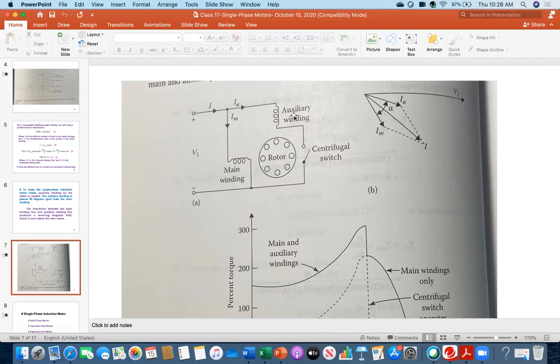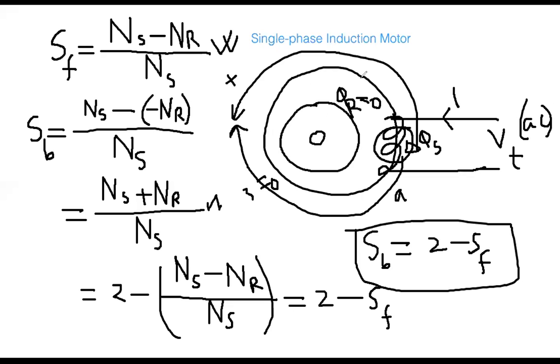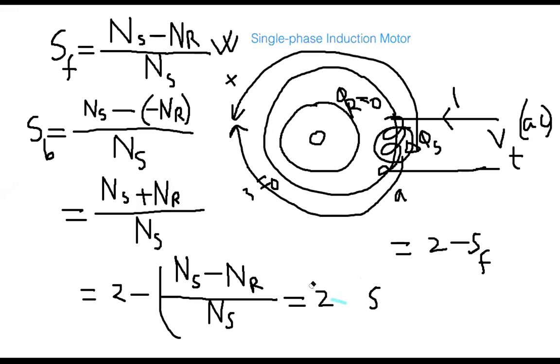So now in real practice, how to do that? Because by looking, it is just a coil, right? It just looks like a coil because I am not showing any resistance here. I am just explaining by looking. That's why in real practice, the main winding is thicker in shape than the auxiliary winding. Just a moment, let me take you to that board. Then it will be much more clear to you. Let me clean up these things.